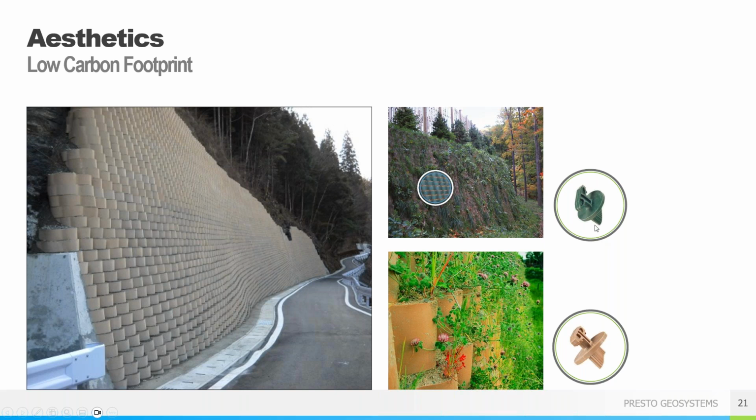Our natural wall keys, as you can see here, most of our vegetated walls are going to be either tan fascia or a green fascia, and those keys really do help it blend in. I do recommend not using a black fascia if you're looking at doing a vegetated wall, because the black will attract heat, which will get rid of a lot of the moisture. So if you're looking to vegetate, I would highly recommend keeping either a green or a tan fascia.